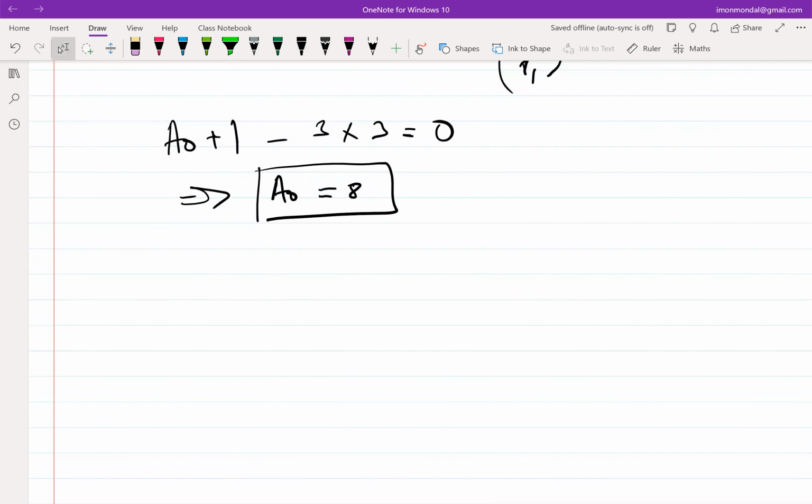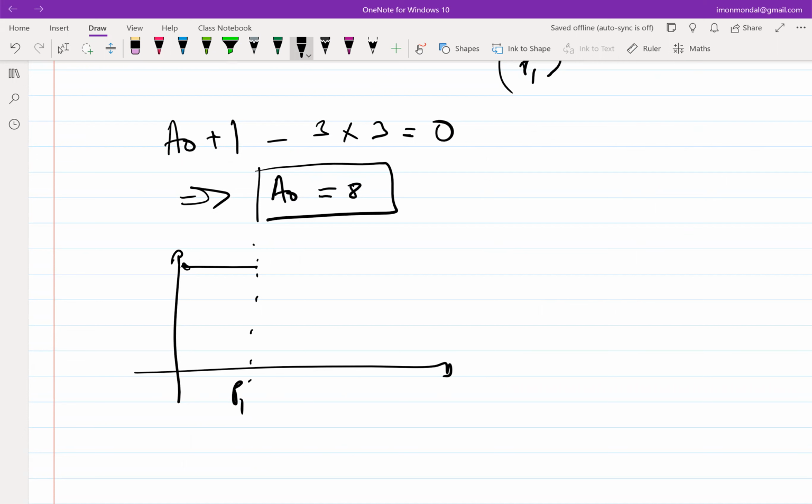Okay, so if you look at the Bode plot, what does this system look like? This system essentially looks like you have all these p's, poles bunched together, which means this goes by minus 60 dB per decade. Right? Again, by the statement that I made earlier, you would want your system to behave like an integrator around omega u loop. So this is your new omega u loop, where it crosses the 0 dB line. But clearly it's not an integrator. You have minus 60 dB per decade roll off.